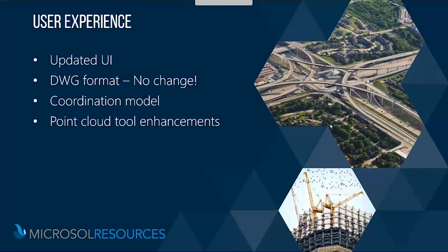Autodesk has been, over the last few years, refining a bit of the way that AutoCAD and Civil 3D interfaces and UIs work. There's a couple of things that they've added from the wish list. Amongst them is the ability to drag and drop some of your layouts. Those of you who do a heavy amount of production work would have noticed that in the previous versions of AutoCAD and Civil 3D, your layout tabs, when they were bunched at the bottom, made it very difficult for you to drag and drop to the ones that were hidden. So that's been resolved.